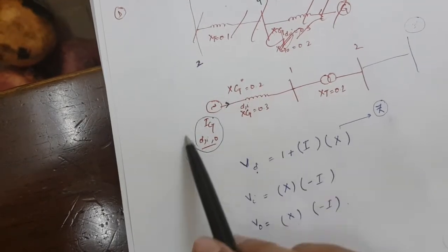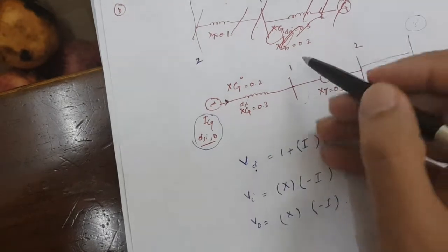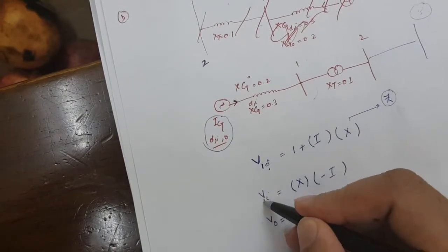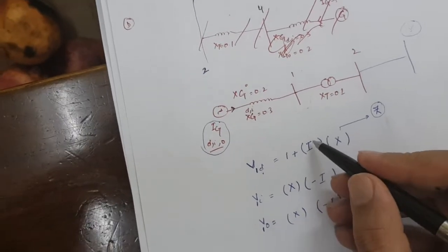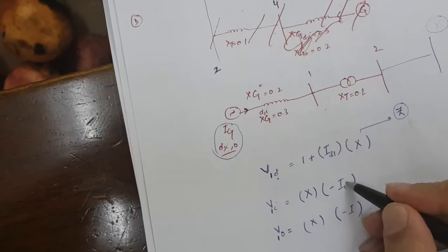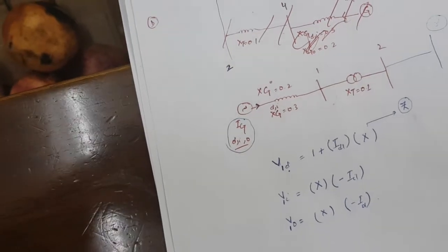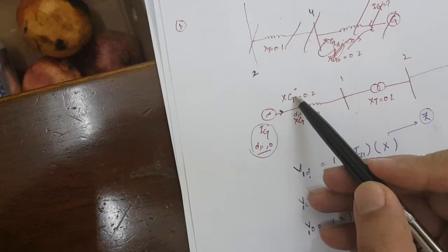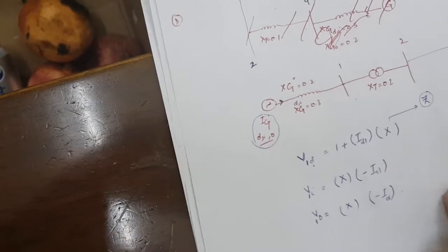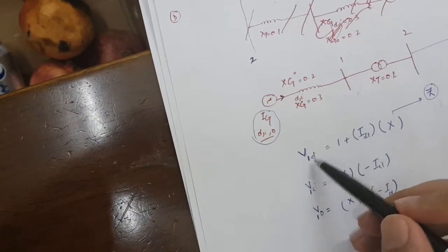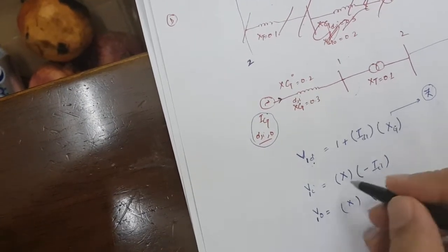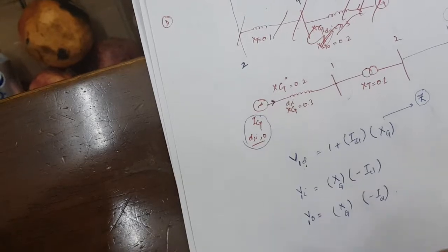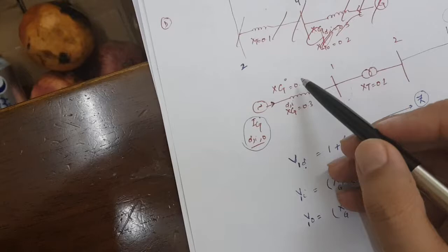In this case, if we have to find the current, we must know the voltages of bus 1. So all these voltages are for bus 1, and consequently this current is the positive sequence I1, or in other words you can say IG, as you wish, you can name it anything. For the reactance you can see this is the positive reactance 0.3, so it's Xg for generator reactance. It must be noted that for positive and negative it's 0.3, but for zero it's different. If you see in the figure it's 0.2.